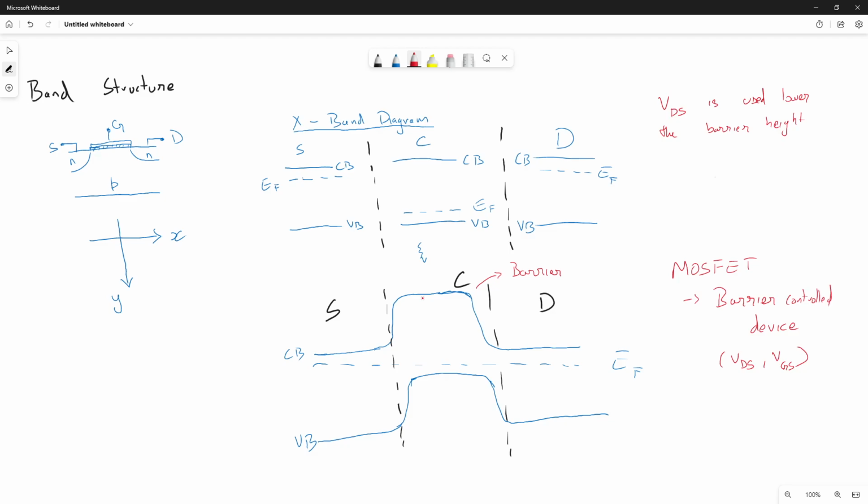So, let me remind you this. Like you said, the barrier will move down faster because you were expecting the current to increase, correct? Yes, sir. But how does the current increase in a depletion mode MOSFET? Through basically inversion. Essentially, my valence band is pulled up so high that it comes above the Fermi level. So essentially, what we are doing is we will try to achieve localized inversion, like from a P type, this material will become N type as Vg increases.